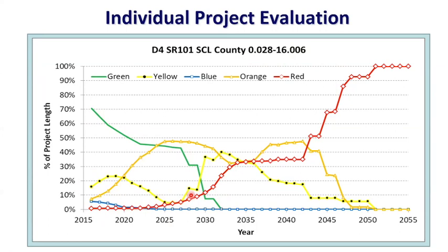Okay, so based on this chart, what kind of improvement strategy can we strategize? So the number one thing is that if currently you don't have any money, you can wait until the pavement becomes crappy. That means you wait until the red colored pavement increases to maybe about 20%. That's our internal threshold, right? So by that time, you probably need to rebuild, or at least you want to do rehab. Okay, you want to do rehab.